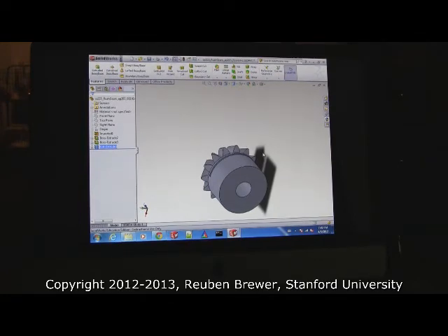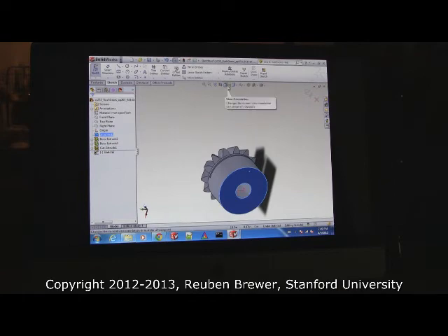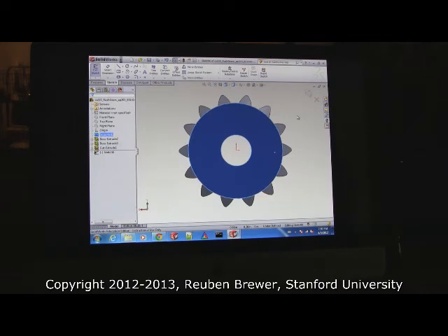Yeah, the reason I'm doing 1 inch is arbitrary. I just want to get a hard cut. Good? Okay. We're about to get to the exciting part, everybody. Okay. Now select this face, Extrude Cut. Now change the view orientation with the normal button so we can actually sketch something.